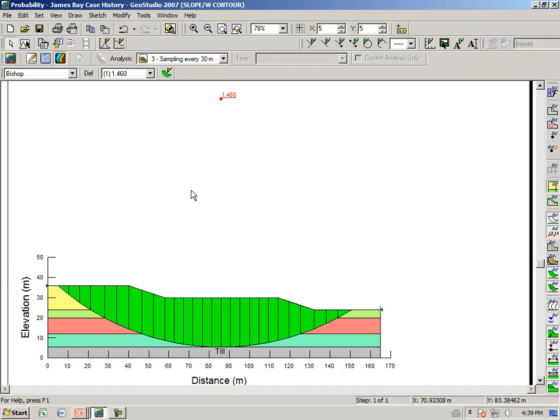The fact is that sampling distance is an important parameter in some cases. The unfortunate part is that to do it properly and know exactly what an appropriate sample distance should be, you need what is called a variogram, which correlates strengths with distance. I won't go into any detail here. Once again, I refer you to the PDF document that goes with this detailed example.